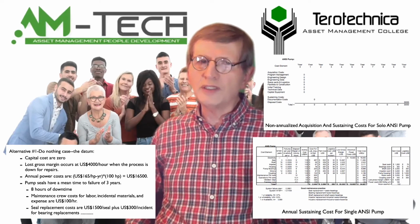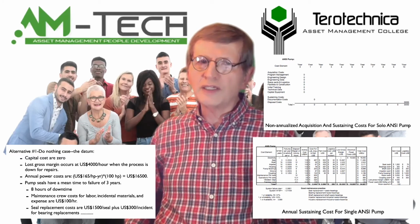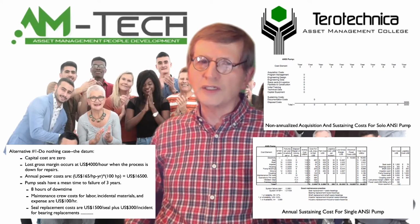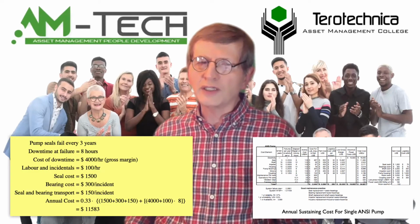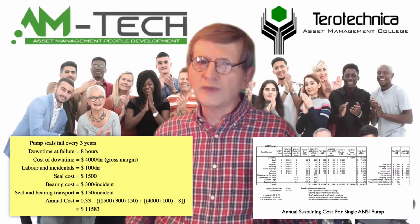Pump seals need to be replaced once in 3 years with 8 hours of downtime, crew costs of $100 per hour, and material costs of $1,500 per seal, plus $300 per incident for bearing replacements, and so on. The annual acquisition costs are 0, but there is a disposal cost of $3,000 in year 10. The sustaining costs are shown in the last figure and come to $54,827 per year.